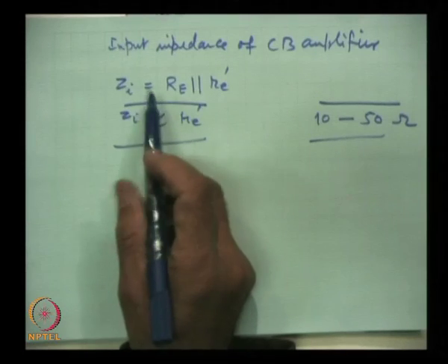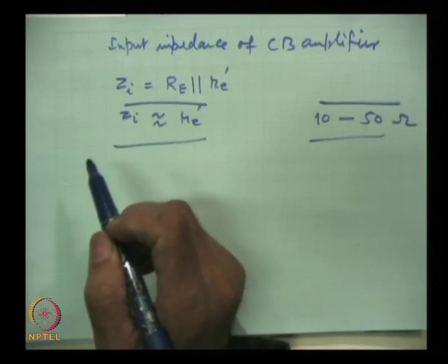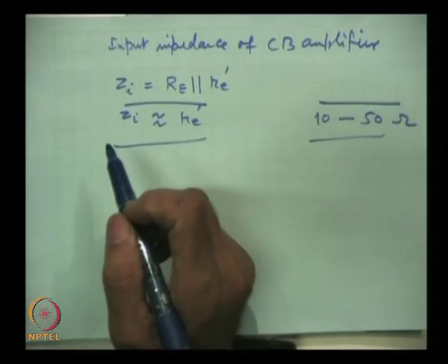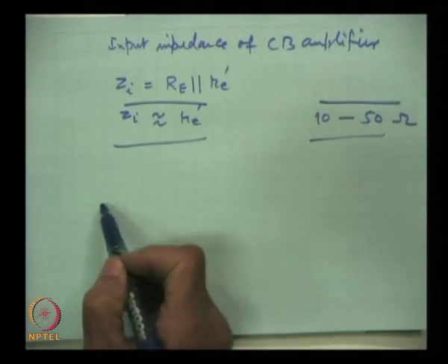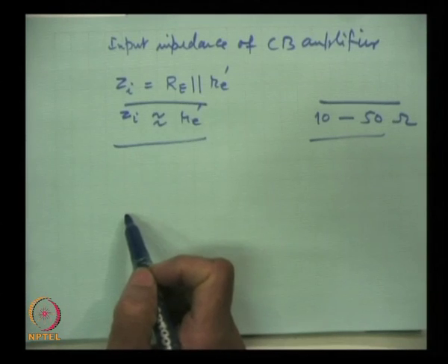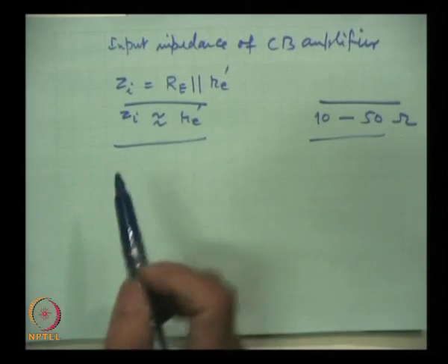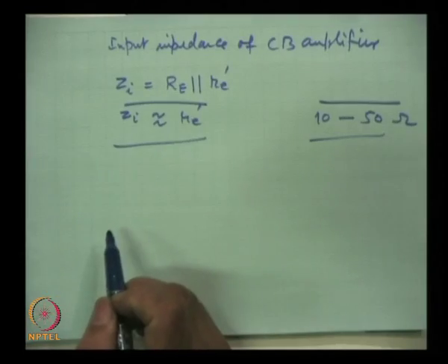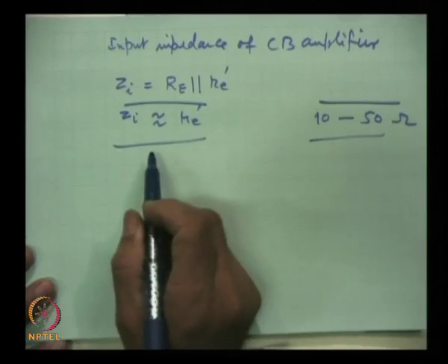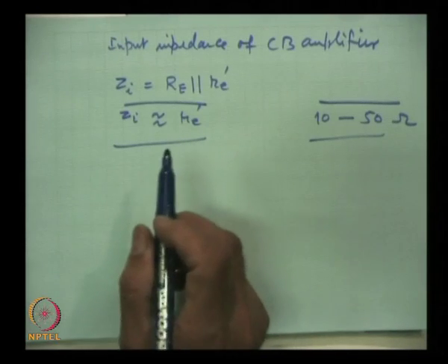If it is connected to other amplifier stages, as we were talking shortly when discussing the applications of common collector, that is emitter follower, we said this will load this. If this is connected to another amplifier having high impedance, then it will load, that means the effective gain will be reduced drastically, and hence the performance of the amplifier will be very poor. So, we can't really do that, and that is one reason that it is very rarely used.